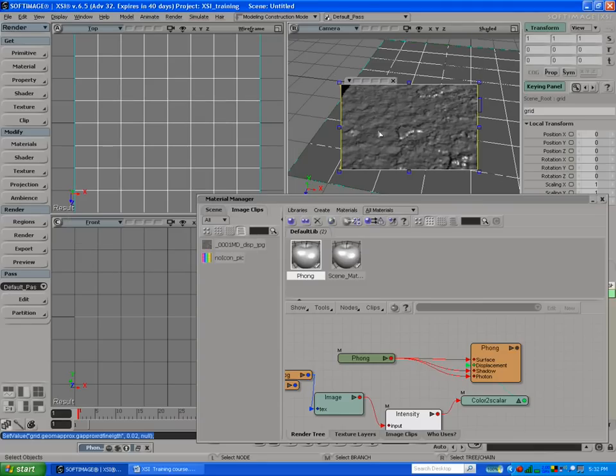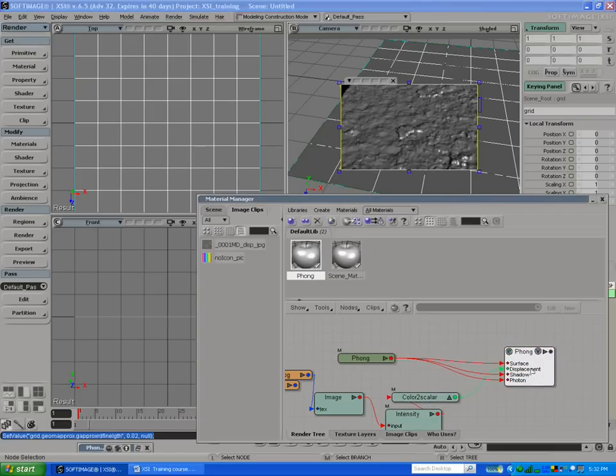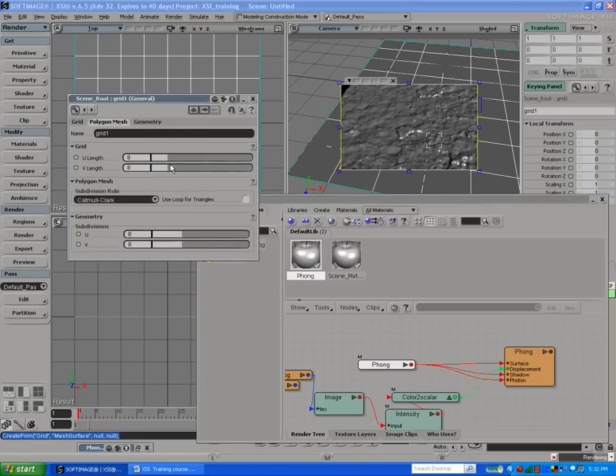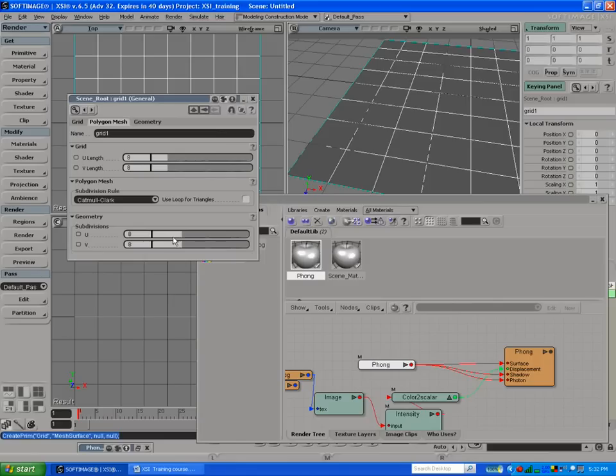That's all pretty nice, but it'd be really nice if I could actually create that geometry and use it to create a normal map. Now if I want to make a normal map from this, there are some techniques you can use with render map. Render map can be used to render out and create a normal map from this object. You can just go here and make another grid. Let's close this down for a second. We'll set this grid to no subdivisions,